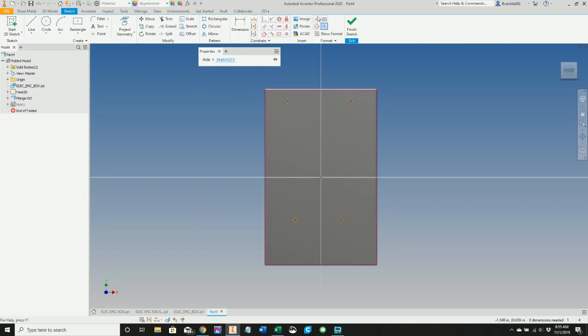First thing I'm going to do is come up to the construction feature. Come over to rectangle, and I am going to create a construction rectangle so that I can snap my center holes to. So I'm going to hit escape to get out of the rectangle function. I'm going to go ahead and just slide these over and connect these since I'm here. So wait until you see the little green dot letting you know that it's fully constrained to that rectangle. So you can see that we can adjust that size. It's based off of the origin point, so there's always going to center these holes.